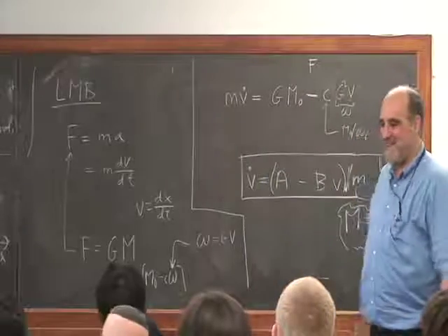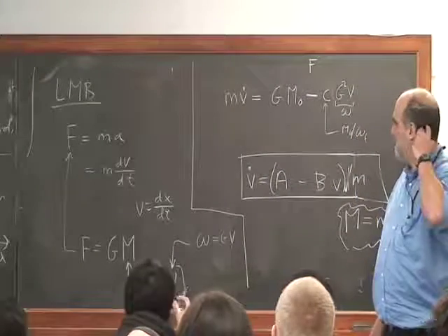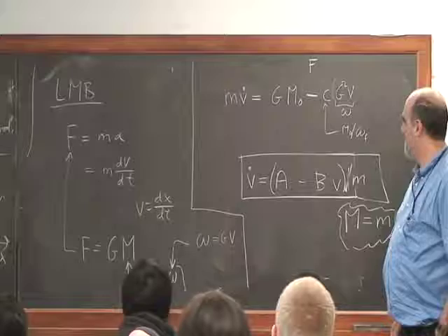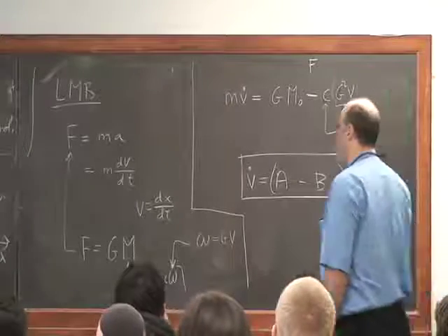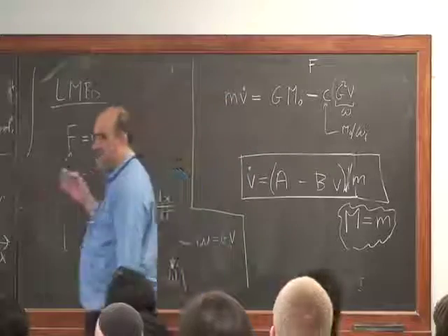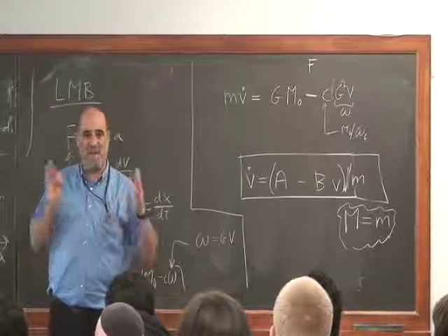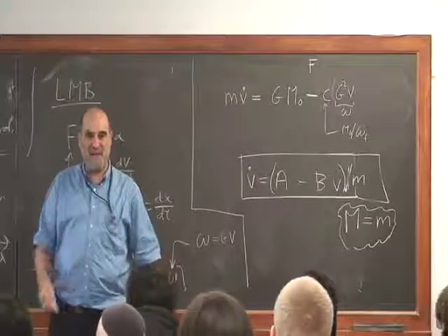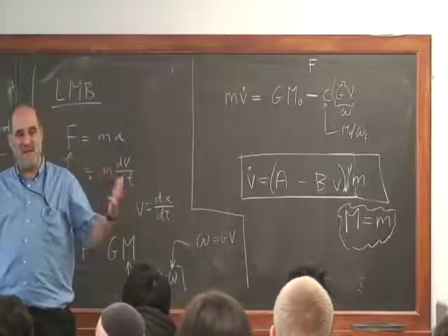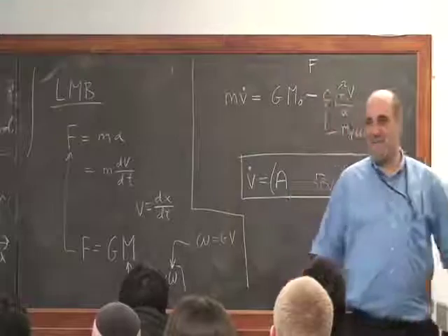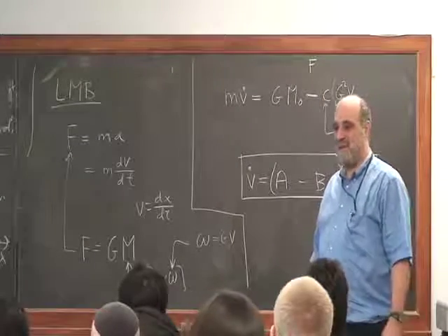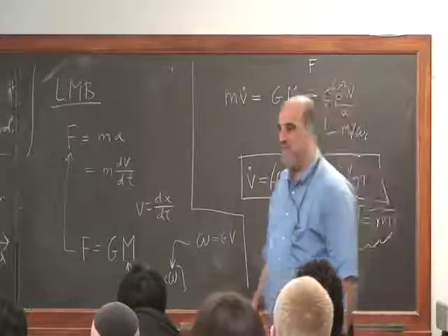Oh no, we've got the same expression using power equal to d by dt of half m v squared. You could use power balance and get the same expression. So there's this intimate relationship between power balance, momentum balance, and kinematics. Just like it applied to the gear train, it also applies to the whole bicycle. That's in problems where energy is not dissipated. If you have friction inside, you cannot use those equations casually.